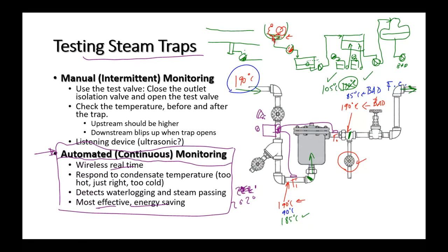Now, some steam will actually go through that pipe as well. So we get both steam and condensate, and it really depends upon where the trap is in terms of its operating sequence. Is it discharging or is it closed? When it's discharging, we can actually get steam flowing from the vessel into the trap while it's discharging. And as soon as it detects the steam, then it stops.